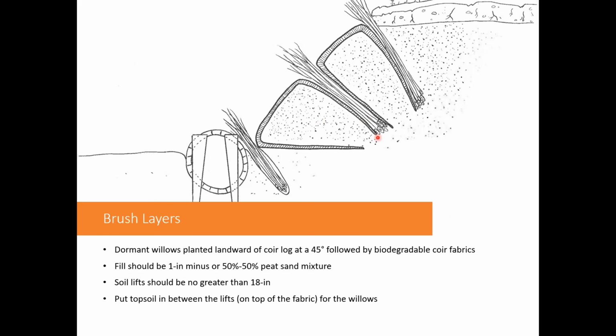And then one thing to note, just because you've put a peat sand mixture or whatever your fill happens to be here, you need to also add topsoil in between. So mix topsoil in with your willow stems.